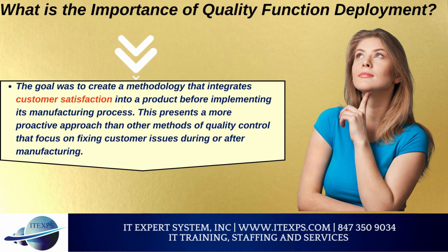What is the importance of quality function deployment? The goal was to create a methodology that integrates customer satisfaction into a product before implementing its manufacturing process. This presents a more proactive approach than other methods of quality control that focus on fixing customer issues during or after manufacturing.